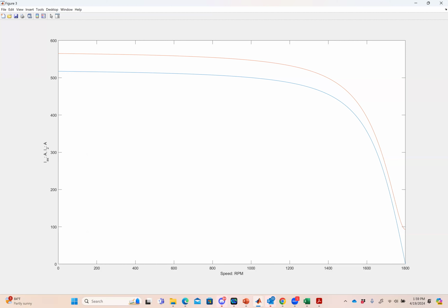Most likely the bigger one. Why is that? Because the other one is like a subset of it. Right. So in other words, it's a current divider, right? The current flowing in is being divided down. So the current in the rotor should be the smaller one, right? Yeah, so that's the blue. The blue is definitely I2. The red is IAS, the current flowing into the machine.